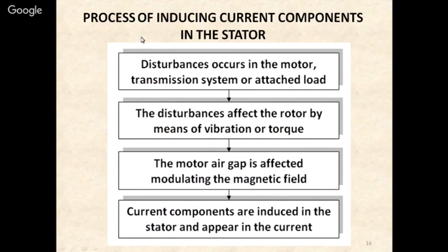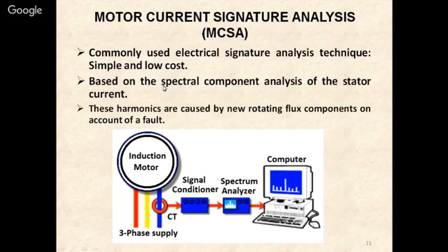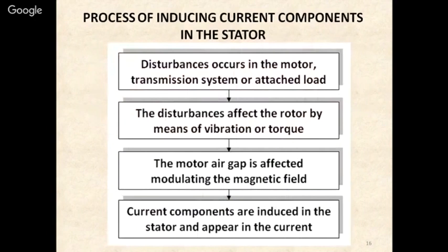So this is the process of inducing current components in the stator. The idea behind this diagnosis is that whenever the motor is running, any fault occurring in the bearing or rotor will cause some stator vibrations. These vibrations will affect the flux of the motor. Okay, so flux will be affected.